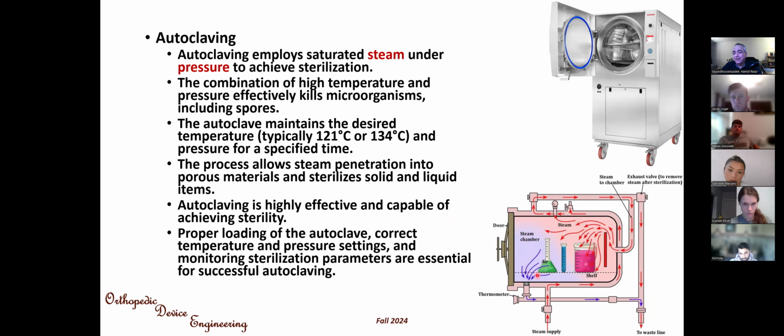First, it takes time to perform the sterilization, 1 to 2 hours based on the device. And also you need the steam to penetrate everywhere. So the packages that are packed inside the chamber must be arranged in a way to allow the steam to penetrate between them.